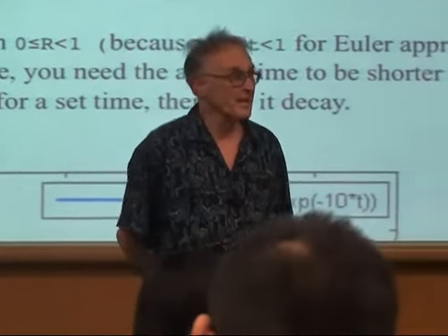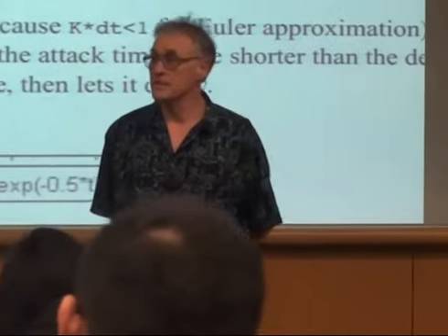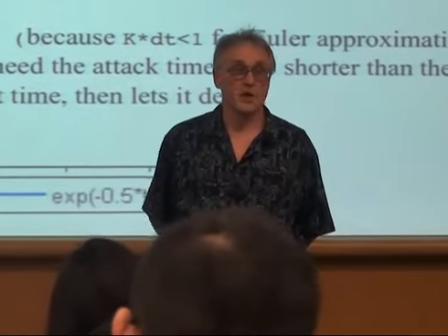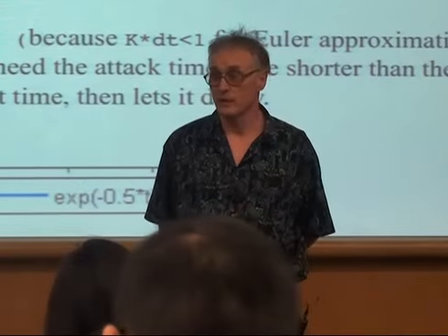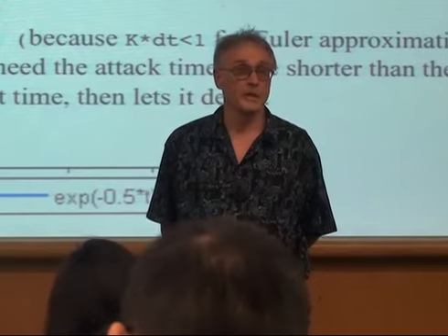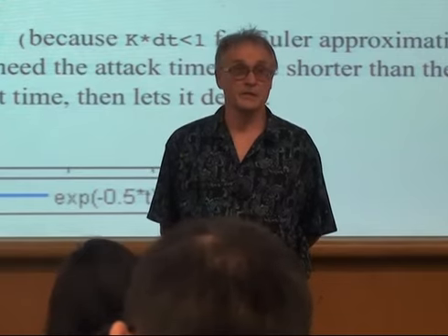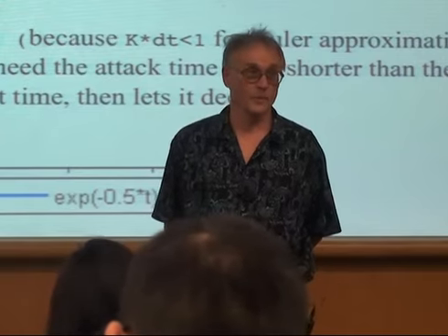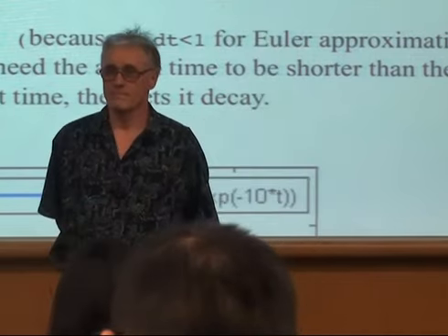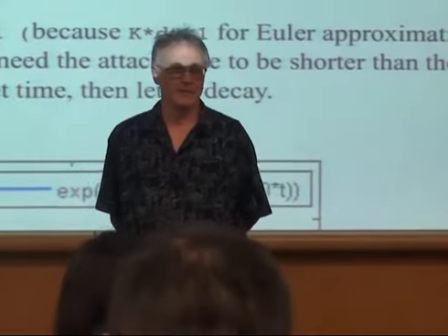If you're going to do capacitive touch, figure out how to use the CTMU, the charge time measurement unit, which is built in and underlies this chip's built-in capacitance touch sensor. 18 channels! But you've got to figure out how to use it because it's not exactly straightforward.